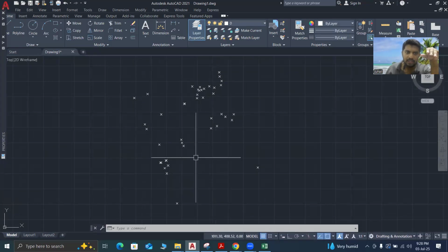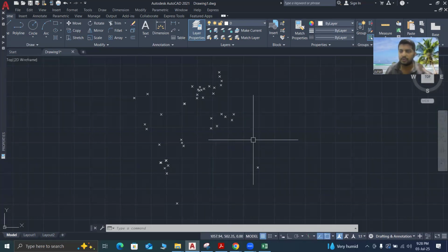If you need to draw this, then when you are doing the total station work, you have to initially draw a prospection diagram of your land. According to the prospection diagram, there will be point numbers. According to the point numbers, you join these points to get a map, and then you can easily plot it.